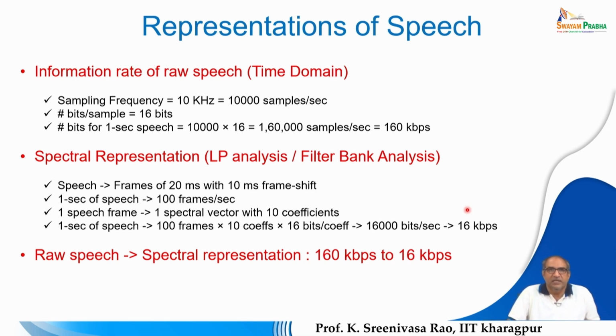Before going to the details, we have already come across the terminology quantization when we are in the process of acquiring a speech signal through a microphone and afterwards converting the continuous speech signal to digital, where we come across the stage known as quantization. It is nothing but approximating the actual amplitude to a known level or known reference value. Because of the finite precision offered by computers, we cannot represent the actual amplitude, because it is a real quantity. Therefore we need quantization. We discussed quantization in that context when digitizing the speech signal.